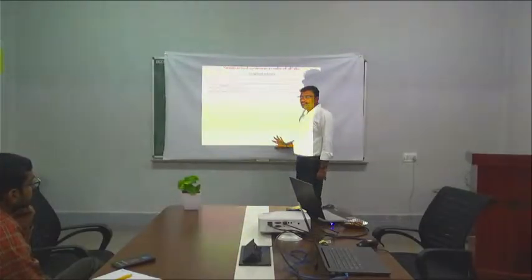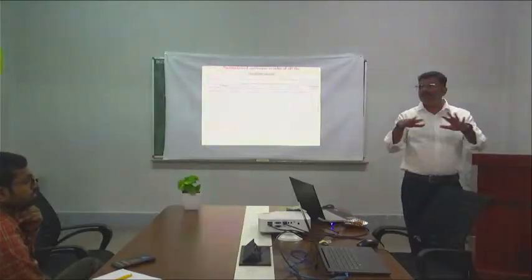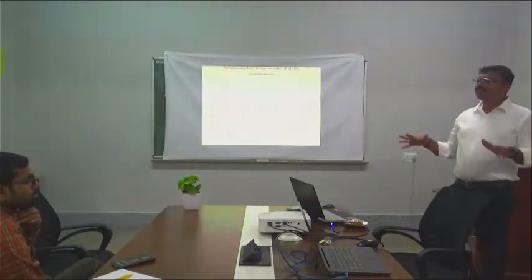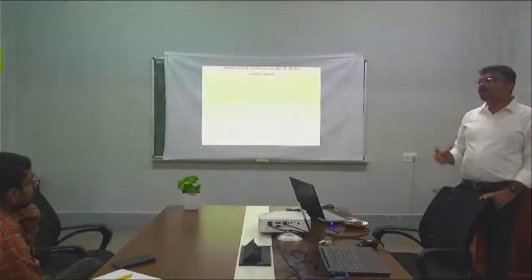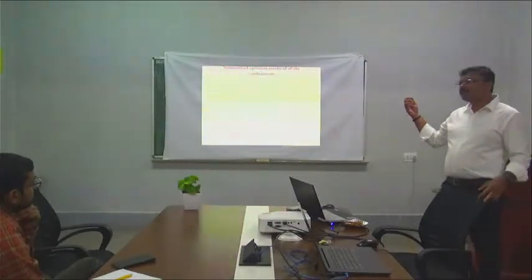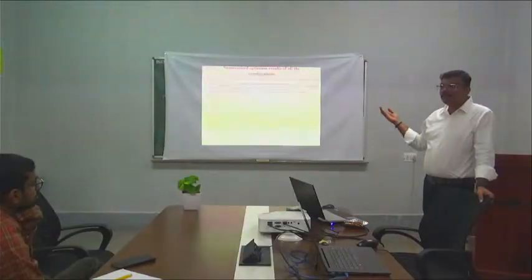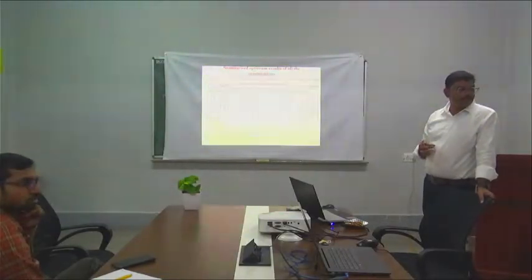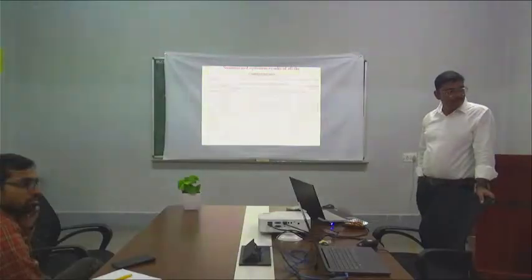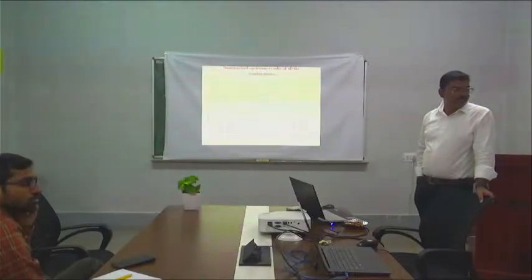What I am thinking, see, when you simulate your microgrid, you try with different options. Out of those options, you are going to extract the best thing. The best thing is based on sizing, based on LCOE value, LCOE unit cost. All those things we are going to consider. For the optimization algorithm, what is our objective function? The objective function is LCOE and NPC, net present cost.